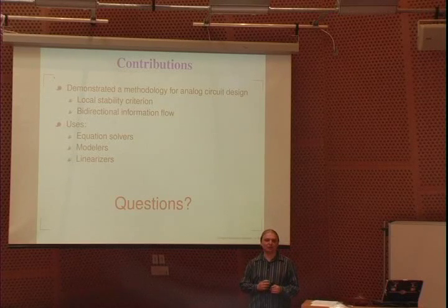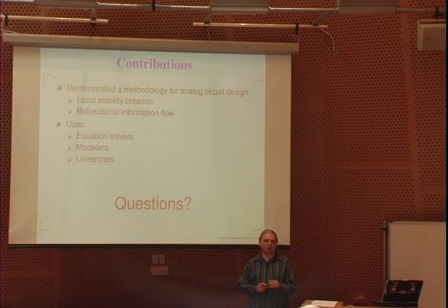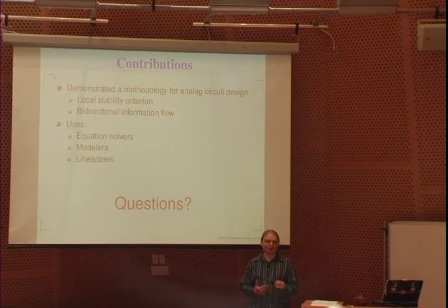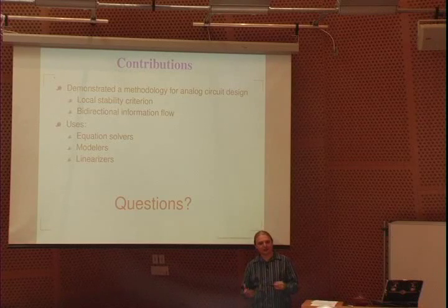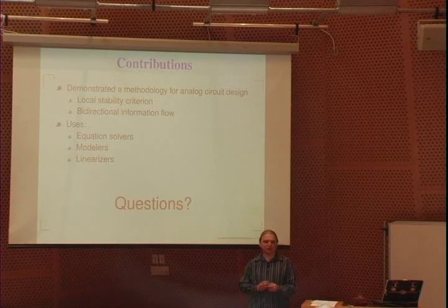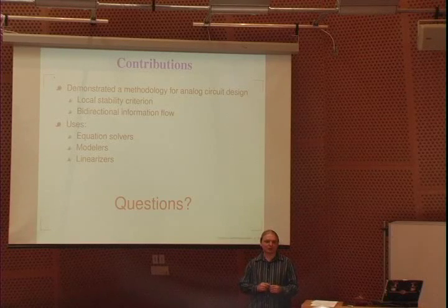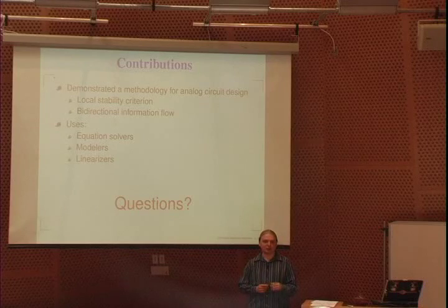There was an interesting paper that I saw that made an analog to switched capacitors with switched currents. The reason that I haven't thought about that very much is that with currents, the equivalent of a capacitor for a current is an inductor, which is a pain to build for analog systems. There are active equivalents, but if you use those, I think that you would lose a little bit in terms of performance or complexity.